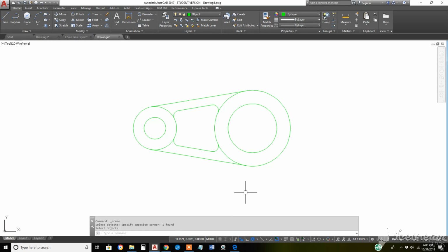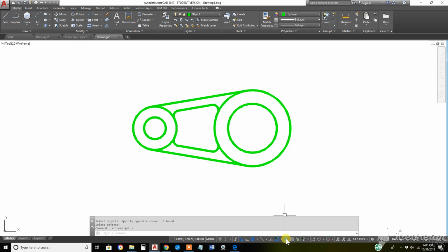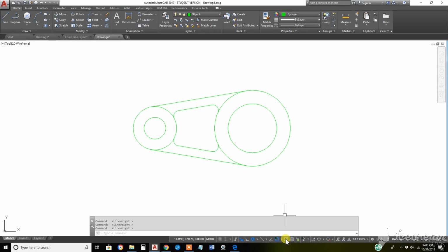Next we need to draw the center lines. By the way, double check, yep, object is set to print out very fat. So let's leave the line weight off for the time being. Next we need to draw the center lines. Let's make current, say, the center layer, and draw lines from top dead center quadrant to bottom dead center quadrant. Hit enter again to invoke the last used command and go 9 o'clock quadrant across to 3 o'clock quadrant.